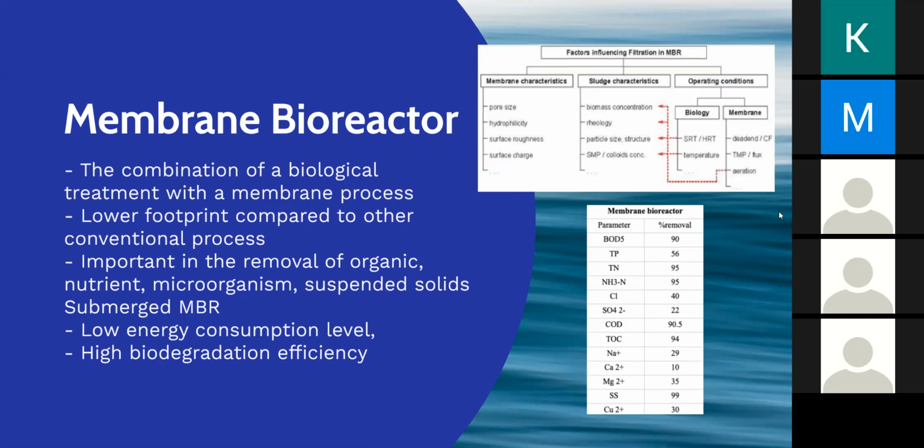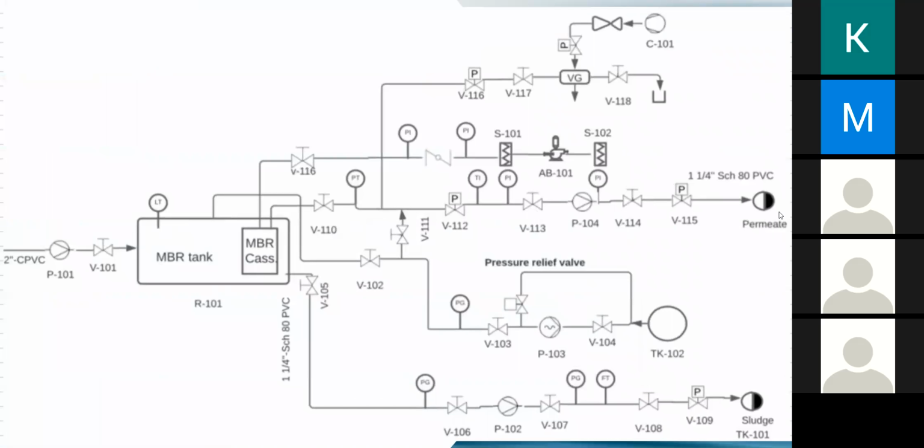Okay, moving on to the P&ID of the membrane bioreactor. The wastewater treatment using an MBR starts once the effluents enter the feed stream and flow into the reactor. Since our design focuses on the submerged MBR, the hollow fiber membranes will be assembled and installed into the reactor. An air compressor is included to operate the systems, and the process blower is crucial in this design for oxygen transfer to the reactor. The reactor tank is where the biological process is happening, and once the water is pulled through the membrane, it will be pumped out to the permeate tank or to the next treatment process. Excess sludge will be disposed of properly according to the sludge disposal regulations.